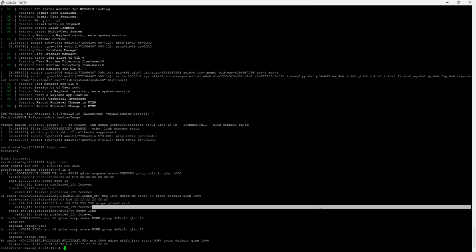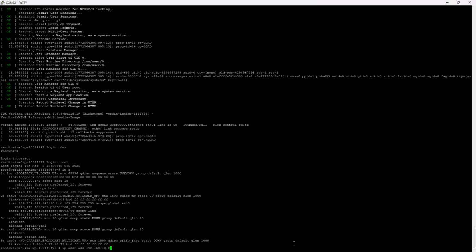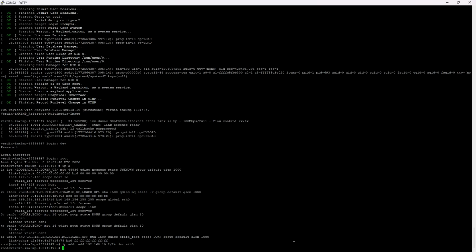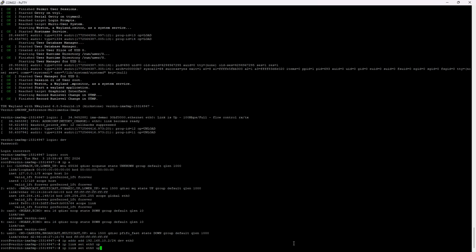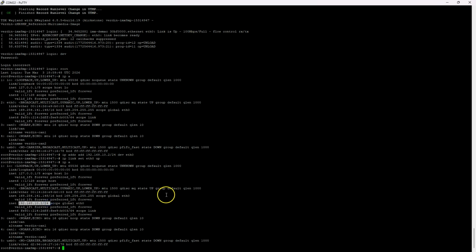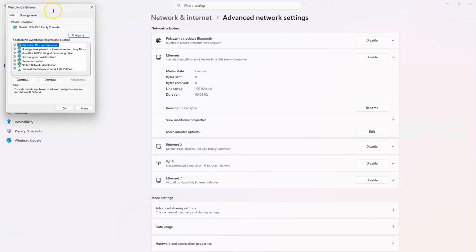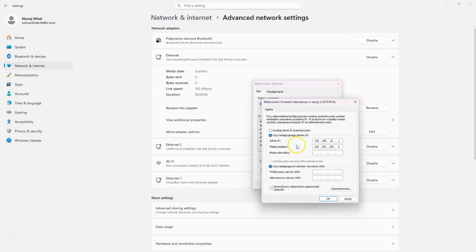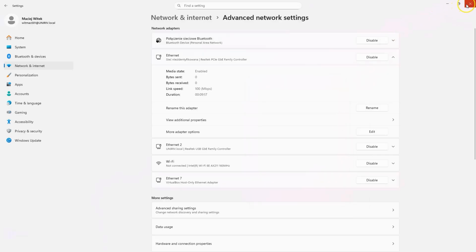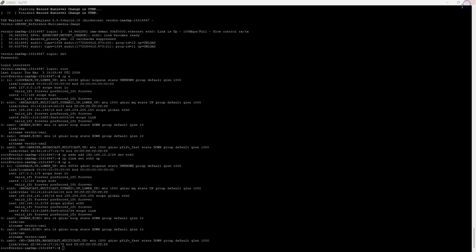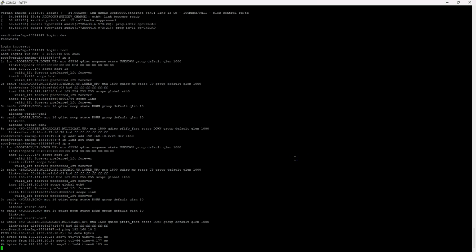overlay file. Next, we configure a static IP address on the host computer. This ensures that the host and the Verdin module are on the same network and can communicate directly over Ethernet. In this example, the host machine is assigned the address 192.168.10.1, while the Verdin module was configured earlier with 192.168.10.2. With both devices in the same subnet, we can now transfer files between them. To confirm everything works, you can ping the 10.2 address from your PuTTY console.